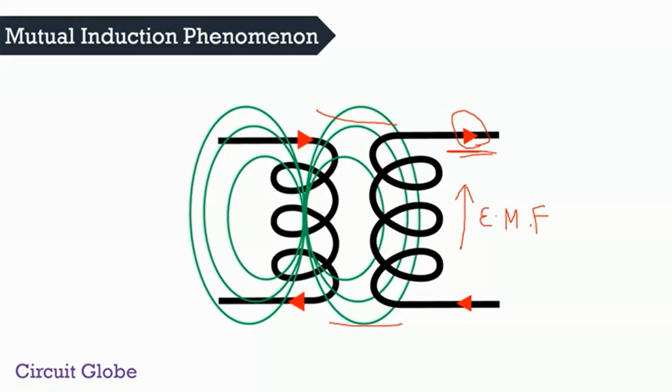Now, for inducing a large magnitude of current in the secondary coil, we need a low reluctance path between the coils. So here in the case of a transformer we are using steel. Friends, the steel provides the flux a very low reluctance path, and because of this low reluctance path the whole of the magnetic flux that is induced in the first winding links to the secondary winding, and an equal magnitude of current starts flowing in the secondary winding of the coil.